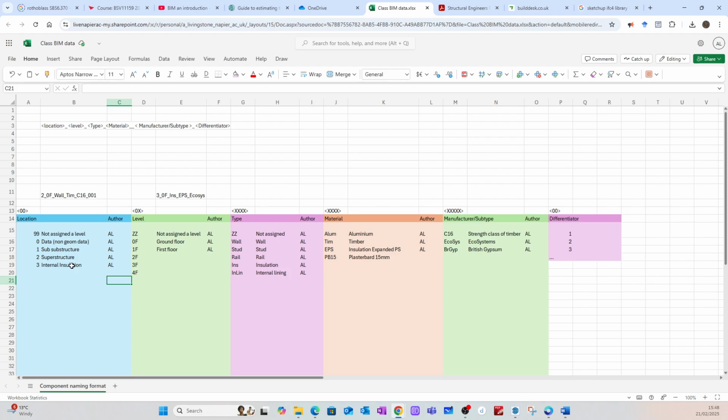And how would you do that as a wood fibre timber and construction roadmap approach? You absolutely can use wood fibre insulation on the external. You have a look online for the various products that would do that, or do internal as I was showing you there. There's positives and negatives to doing the insulation external and internal. Pick one, go with it. Get the U values for the walls, floors, roof, ceiling, windows, and the air permeability. Think about the air permeability.